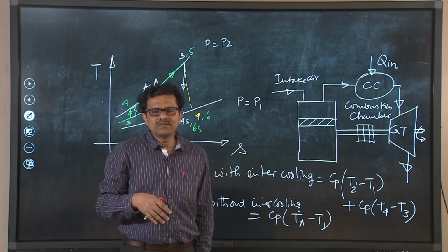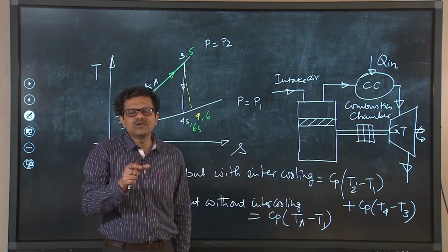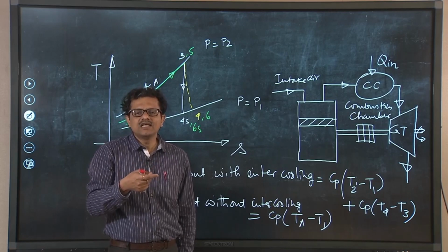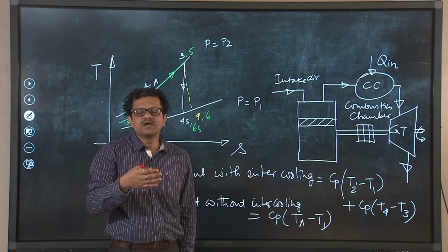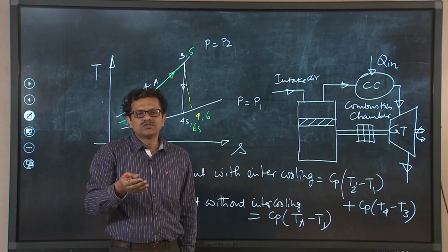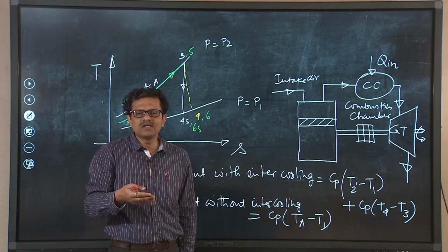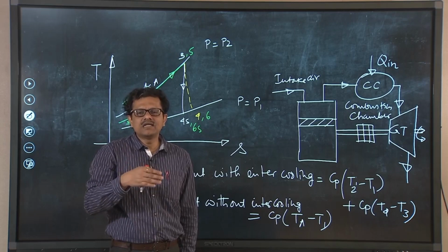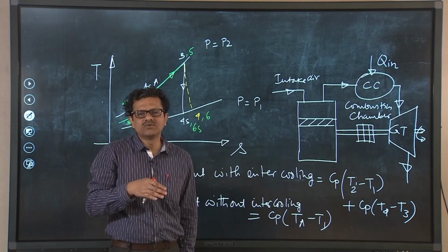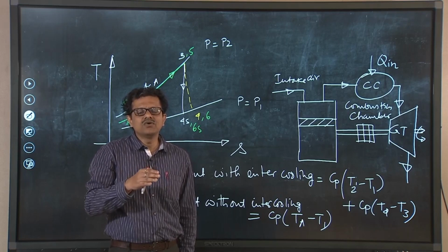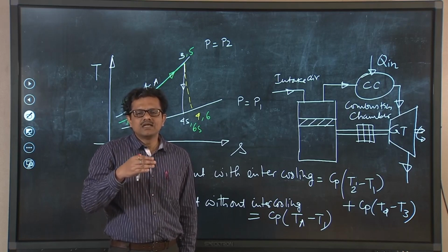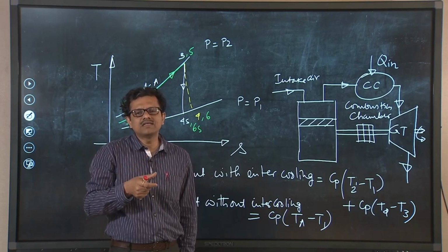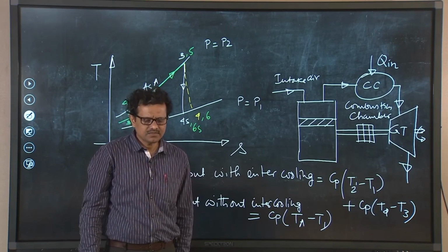Not only that, as we have discussed, for the intercooling unit we need to supply water or any other coolant, and for that again we need to have mechanical components. So, installation of those mechanical components as well as maintenance will eventually increase the total cost associated with this unit, and hence even though intercooling effect increases work ratio, the gross impact is the reduction in thermal efficiency.